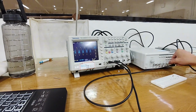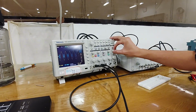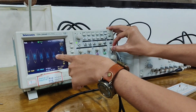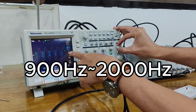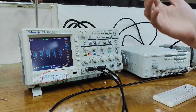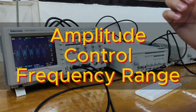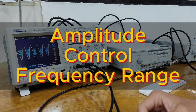When I turn to the maximum amplitude, the frequency range is from about 2000 Hertz to about 900 Hertz, so the range gets wider. In conclusion, the amplitude controls the frequency sweep range, not the absolute frequency.